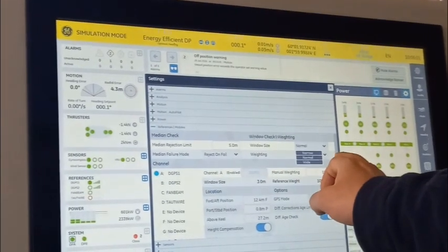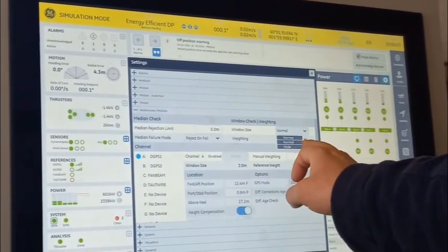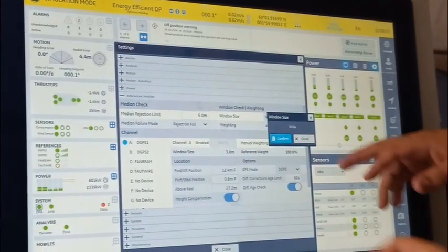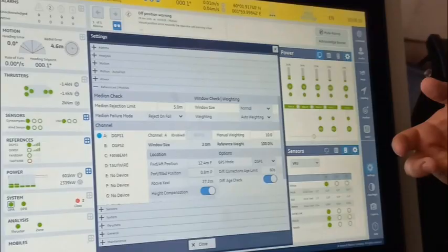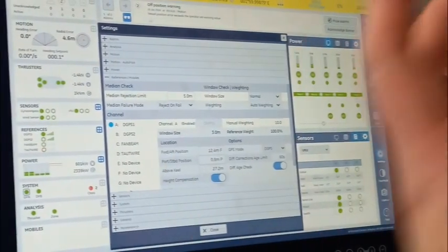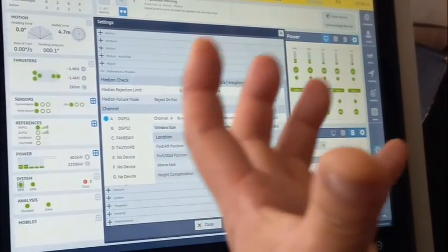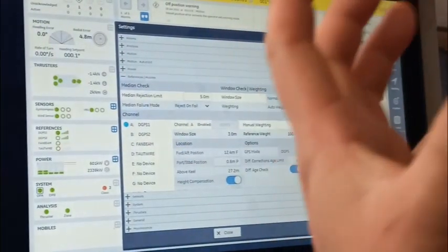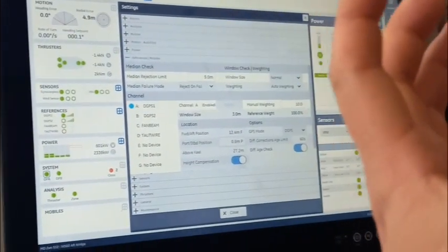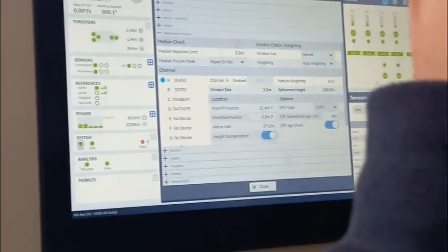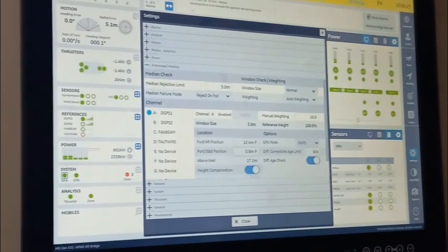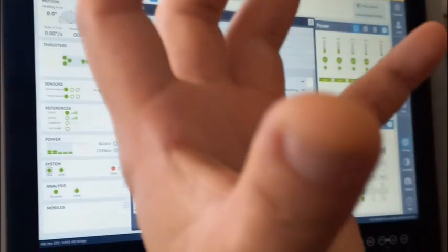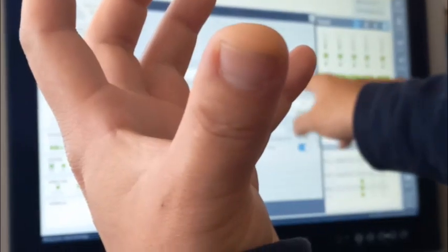You can actually change the options here. We speak about the weight of the signal. Weighting. You got 2 DGPSs. Yes, the weight. Normally, auto weighting, each one will be 50%. If it's having bad signal on one, the controller will distribute weighting more on the reliable one. So it automatically goes to automatic. That's what it says. Auto weighting.